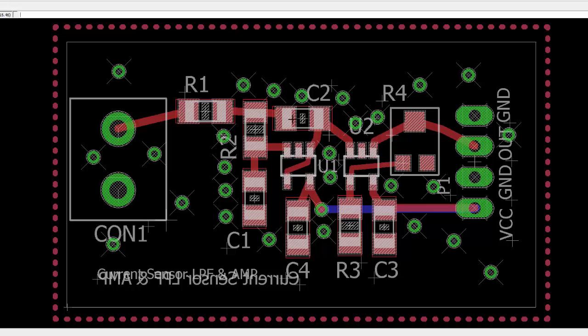Notice that just like in the schematic, the 2 pieces that are close to the op amp, I have them really close to the op amp in the layout, just like the data sheet instructed. Also, I made a bigger trace than the default trace in Eagle, once again, to reduce parasitics. So I could make it even bigger, but I wanted to make it so it fits the pins on the op amp. So once again, I made the traces a little bigger to help reduce those parasitics. Also, I kept the power supply, VCC, this is VCC coming in here, I kept it separate from the main signal path, once again, to reduce noise from getting on the signal path, just like it mentioned in the layout tips.